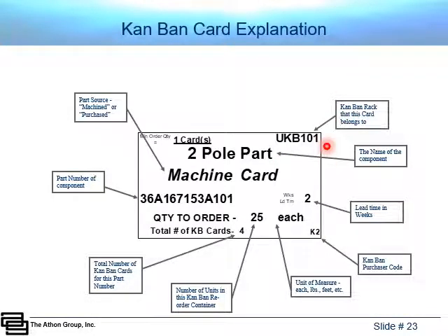Now you'll notice in the MRP system, we typically have a mezzanine structure that is not dedicated. You can put parts anywhere in the mezzanine you want. That has its advantages and it has its disadvantages. A Kanban system, though, leverages the idea that we have a planned maximum amount of inventory we could ever have for that particular part, and then we dedicate a location in a mezzanine where we're going to keep that part.